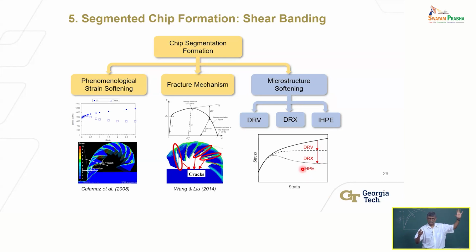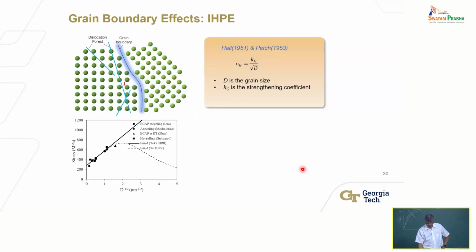But that fails beyond a certain point in some metals. Below a certain grain size, at nanostructured grains, it's been shown that the opposite happens. It starts to soften. That occurs because of grain boundary sliding and much more complicated effects. But anyway, you can account for this semi-empirically, which we have done.